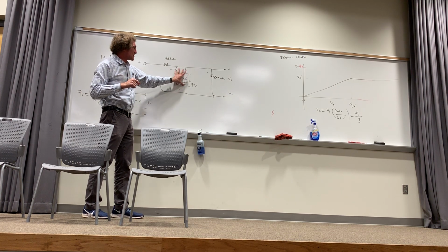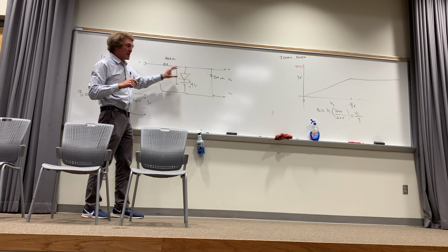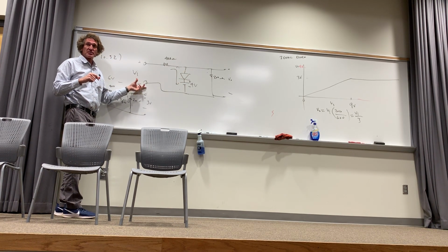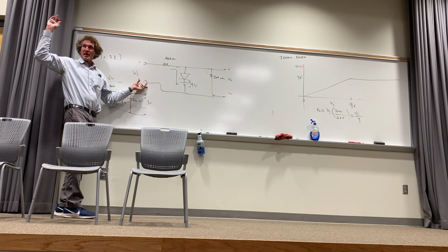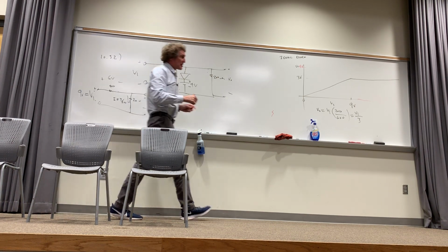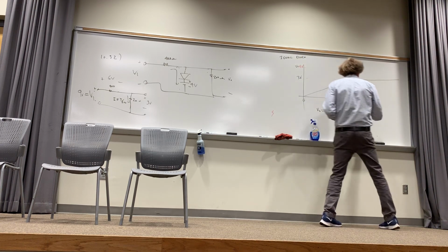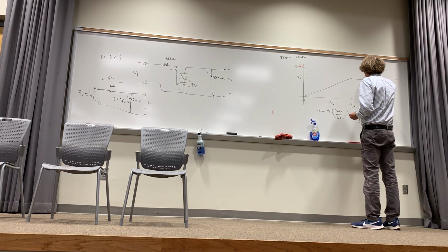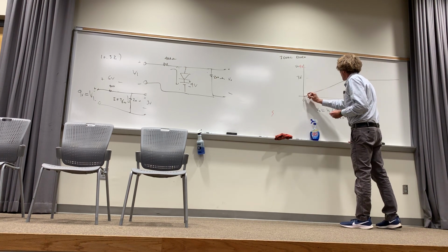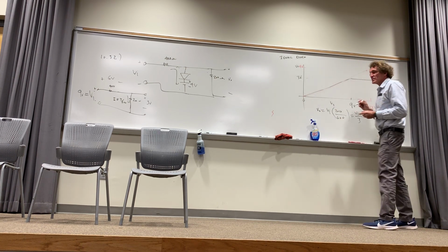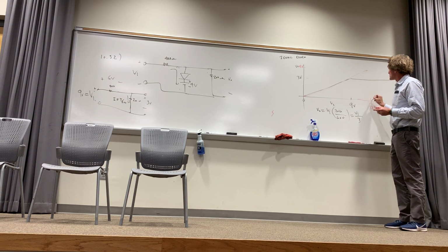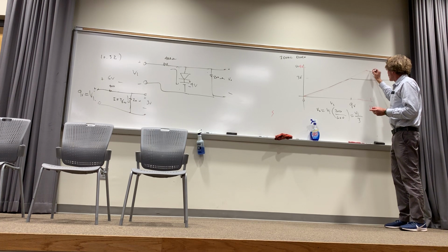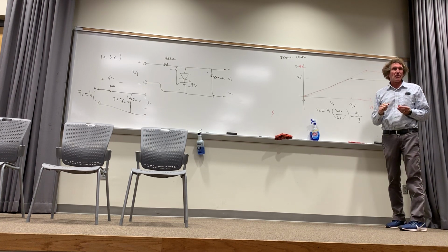I have to find out where this occurs. So if this is 4 volts, then my input would be 4 times 3, or 12 volts. Do you agree with that, everyone? How many see this? It would be 12 volts. I'd come out here and say, if I did that circuit, I would look at 12 volts, and my output would track this exactly all the way to 12 volts. And then what happens, class? No matter what I did, it would still be limited to 4 volts, right?